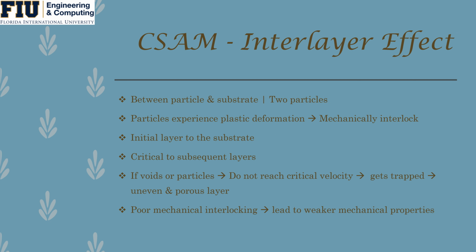Another key aspect of the CSAM system is the interlayer effect. This occurs between particle and substrate as well as particle and particle. As mentioned throughout this presentation, these particles experience plastic deformation to allow them to mechanically interlock with each other. It is very important that the initial layer on the substrate is uniform and free from porosity in order for the subsequent layers to also be uniform and free from porosity.